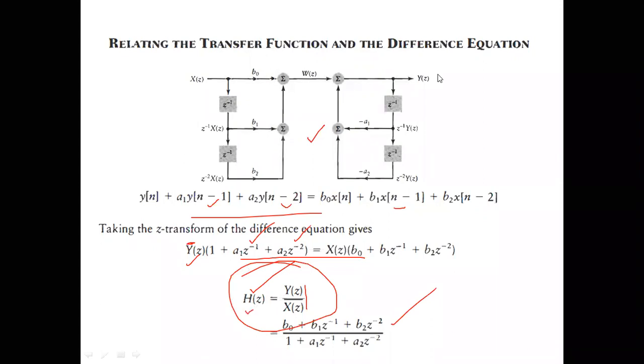So what all things can we do, by the way? Why are you interested in the transfer function? You have studied transfer functions in your control systems also. Here also, once again, you are studying the transfer function for discrete time systems. Whatever you are studying in control systems is mainly for continuous time systems. Here we try to do something similar for discrete time systems, by taking the Z transform, the ratio of the Z transforms Y(z) by X(z).